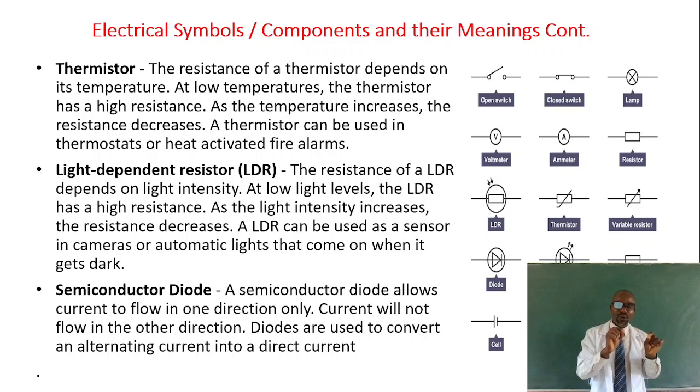No matter how small the current is, it notices that, hey, current is passing by. It detects it. After detecting it, it measures it, tells you the quantity, the amount of current passing at the moment. Unlike an ammeter, an ammeter doesn't do that. An ammeter just measures but doesn't detect current. And that should be anchored on how sensitive a galvanometer is. So a galvanometer is more sensitive than an ammeter. We're going to go into that as time goes on, all right?